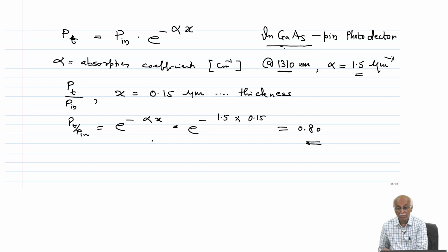But as you start increasing the intrinsic layer thickness to improve the absorption, you end up with a diffusion problem, because now the electron which is produced will have to travel a longer distance till it reaches the n type layer. But in the meantime it may get absorbed or diffused because of the electron interaction with the material. So, basically diffusion also comes into the picture.